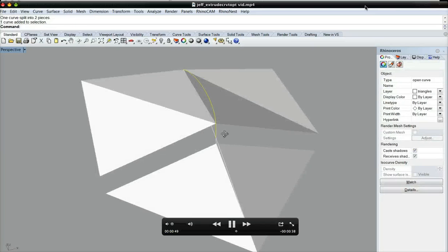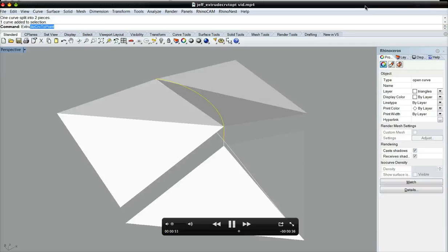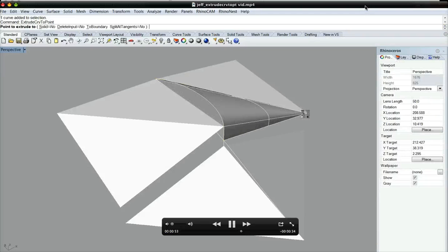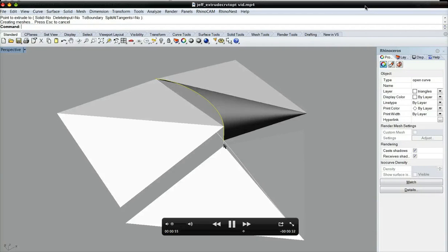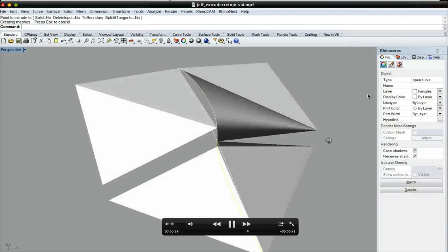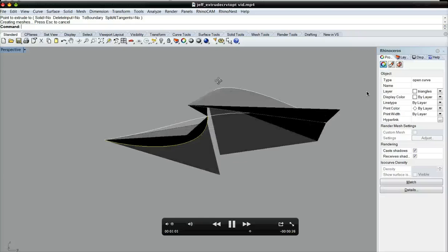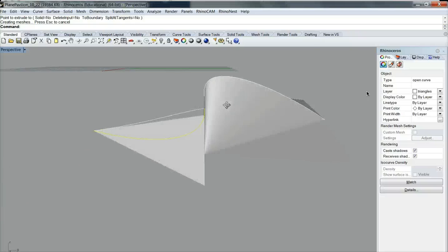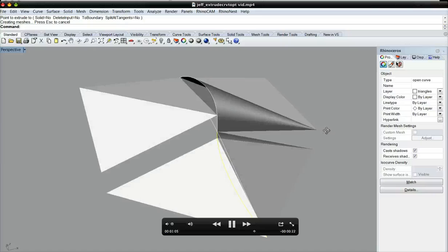And then the command here, extrude curve to point, was important because from the way I was creating these curves one at a time, or these surfaces one at a time, I know that they had a single iso curve, which means that these surfaces only had a single curvature, and it's not a double curvature surface that would be unflattenable and therefore uncuttable on the laser cutter.